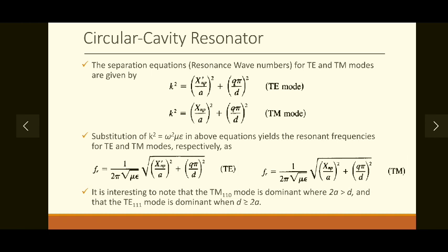But cavity resonators are used only at microwave frequency. At lower frequency we can use a simple RLC circuit. Now the energy confined within the cavity is represented by L and C, and the energy dissipated will be represented by resistance.